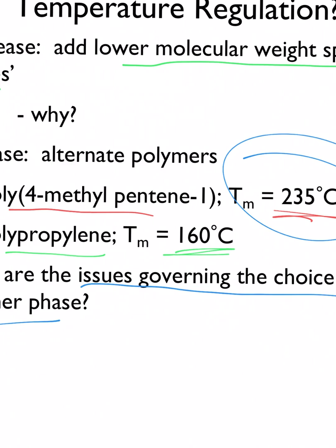Coupling agents, yeah. So we have coupling agents that work for us. We know we have to have them because otherwise we'll get air between the carbon black and the polymer. So we know we've got to have something. And in this case, they may help control the microstructure as well and how it responds to gravity. So we really need these coupling agents.